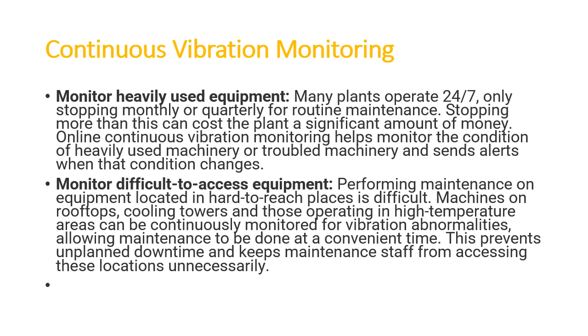Also, continuous vibration monitoring is important for machines which are hard to reach, in very difficult locations, like machines on rooftops or on the cooling tower. Those operating in high temperature areas cannot be continuously accessible to persons. It is better that we install some sort of vibration monitoring on them.